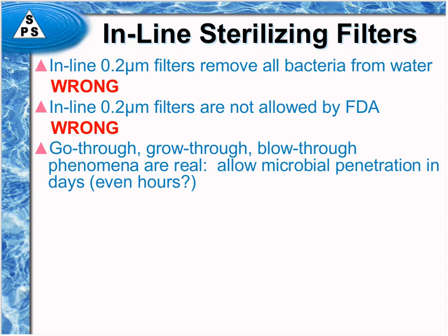But as they work their way through the filter with successive pulses, they will eventually get through to the other side. This happens with peristaltic flow going through filters, and also happens with intermittent on-off operation of filters. So be careful if you don't have continuous flow going through your filter. If it's intermittent flow, you set yourself up for the possibility of forcing organisms to go through.